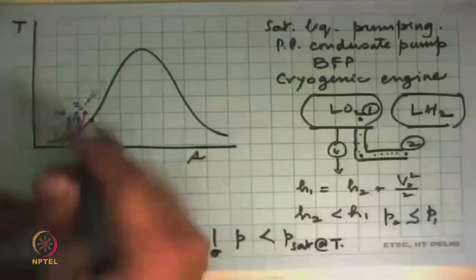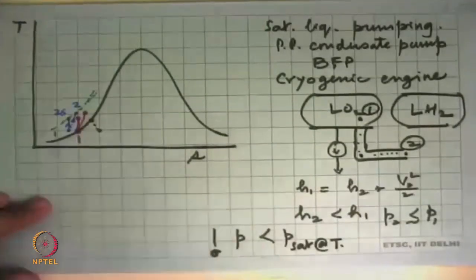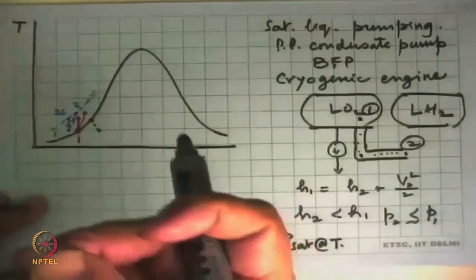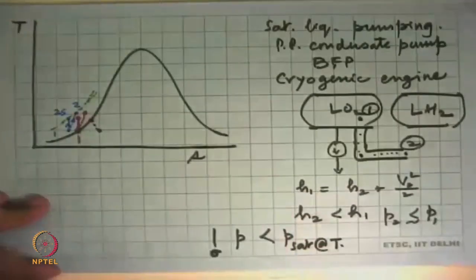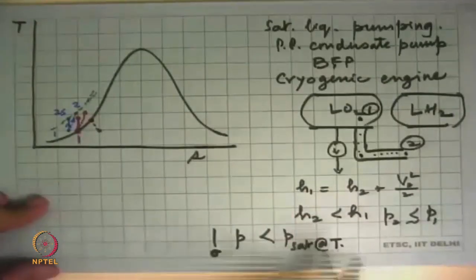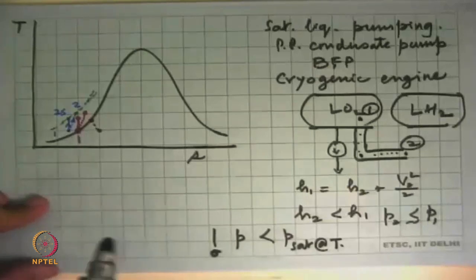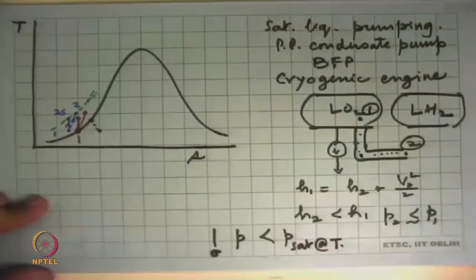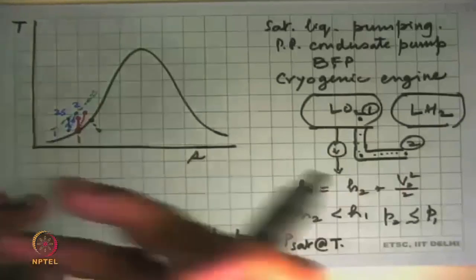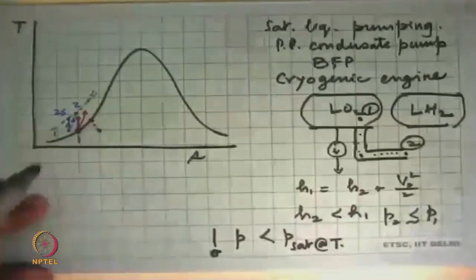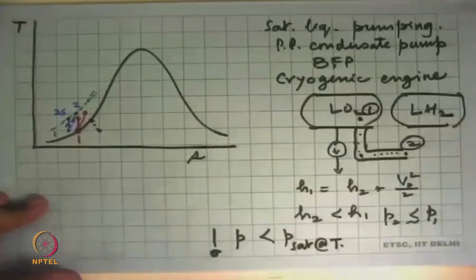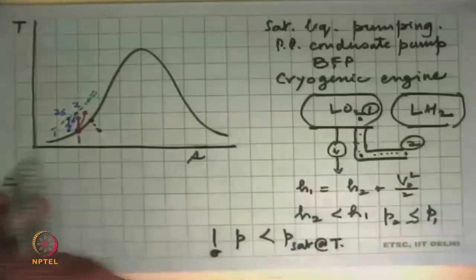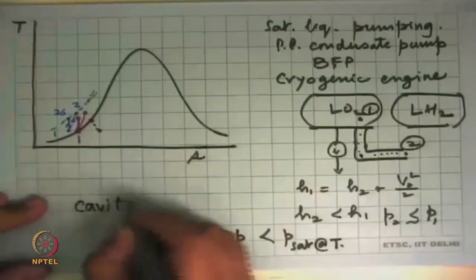So even in a pump like this, where it is taking compressed liquid and you have an impeller that is rotating very fast, very close to the surface of the impeller, the velocity is very high, in which case locally the pressure at that point will be less than the saturation pressure at that point, and you could have a vapor bubble being formed. The moment this vapor bubble moves out into a zone where the pressure is more, it will compress suddenly and it gives out a shock wave, and that's why you will see that some pumps sometimes make a hammering sound, that there's something being hit inside it. There's nothing hitting it, just that this device is happening, that vapor is being formed, and this is called the issue of cavitation.